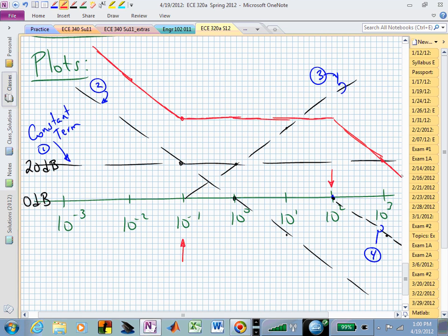And remember, that was our Vegematic. We set it and forget it or some such thing. The slopes and the magnitude, once the magnitude breaks, you never have to turn it off. It's always on. Is that making sense? And that red line then is what MATLAB should generate for you if you plotted the magnitude plot. Now this is an approximation. MATLAB would give you the exact answer, or PSpice. If you did a frequency response of this transfer function, you should expect 40 dB of gain at omega equal to 1 radian per second.